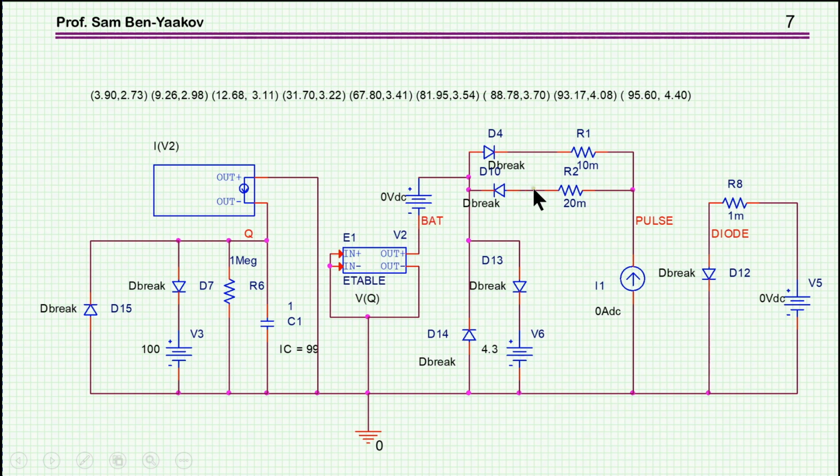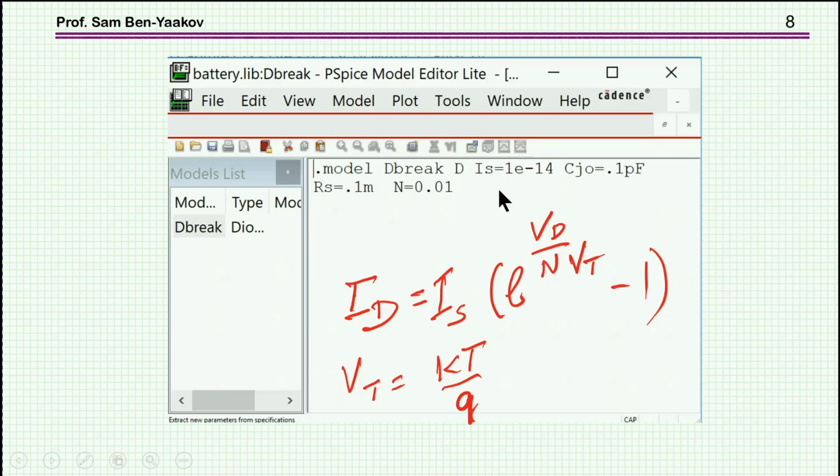And then we have the two diodes, which are sort of estimated. Now, I just took these two values for the example I'm showing. Now, in order to get rid of the diode voltage drops, I've actually modified the diode. You can do this by right-clicking an element like a diode and then choosing Edit SPICE Model, and then you'll have this window coming up.